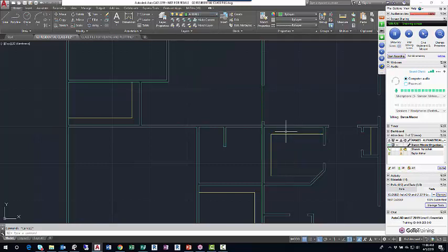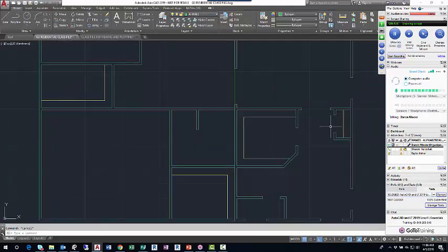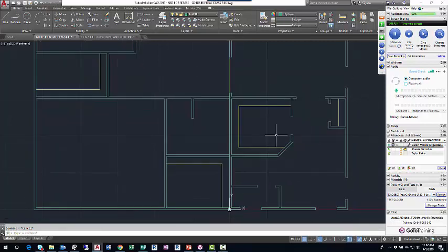And then another way is, if I already have one shelf line or one yellow line in my drawing, I can use the Match Properties tool on the Properties panel. I'll go Match Properties, left click that shelf line, left click one of those wall lines, and that matches the properties. That would be match layer? Yeah, it would match layer. Well, actually, there's one called match layer, right? Match layer would probably work too. I've never used that. Let me try that.